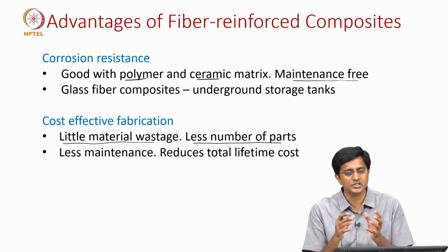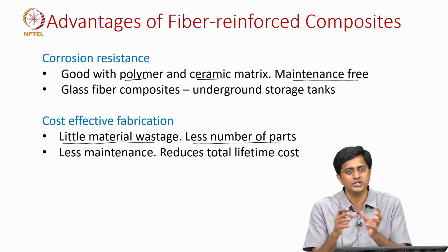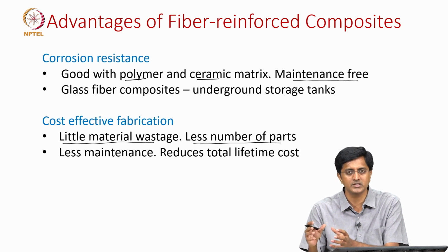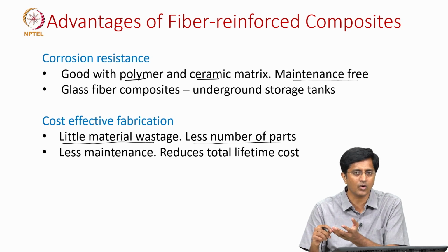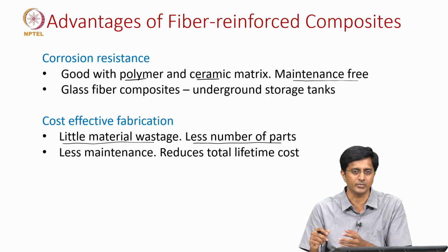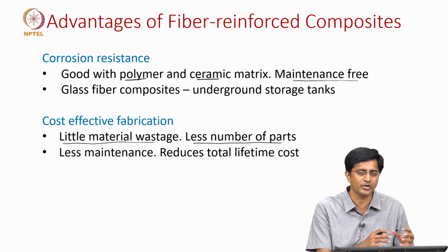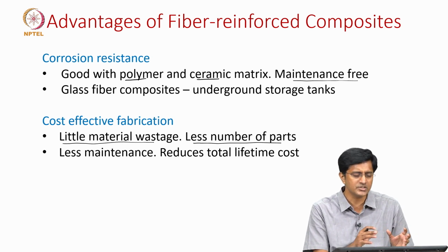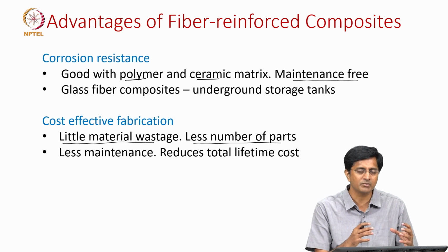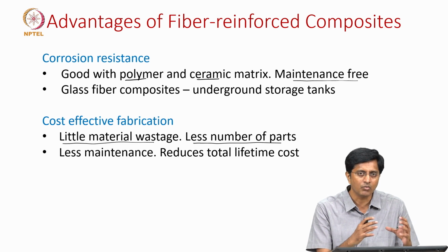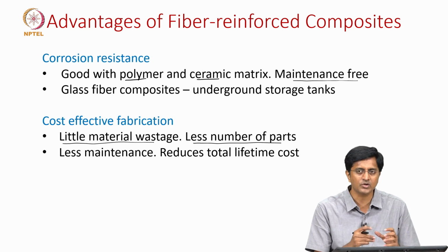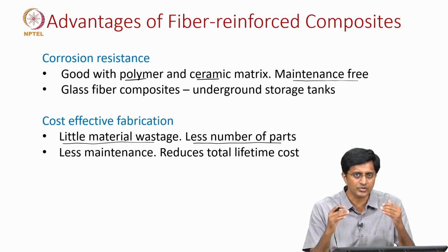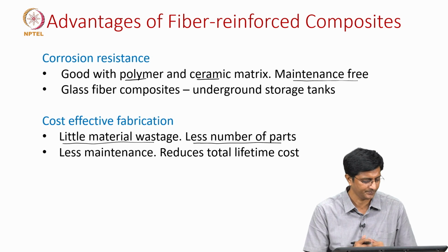So, let us say the same structure is made with composite and the other designed with metals. Usually the metallic structure will have more components because it will have lots of, let us say, rivets for example, but in composites those can be bonded. But not just this, there are other ways. The manufacturing methods also ensure that composites are usually prepared as one single component instead of joining, which means there are fewer components. When there are fewer components involved, of course the overall costs also come down.